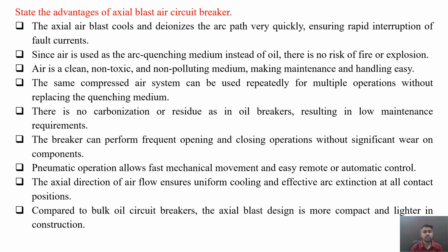The axial direction of airflow ensures uniform cooling and effective arc extinction at all contact positions. Compared to bulk oil circuit breakers, the axial blast design is more compact and lighter in construction. So these are several advantages of the axial blast air circuit breaker.